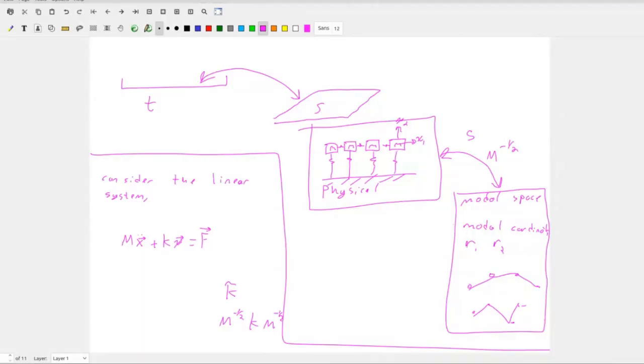And to do this, we're going to go down into our modal space, get a solution, and bring it back. And in the modal space, we can truncate modes that we're not interested in. Because if you go to a testing laboratory and you want to get a time series response to measure fatigue life on the wing of an airplane, how do you do that? You can do that statistically, but that's no fun. No one trusts the statistics. That's why those people make a lot of money and give you huge uncertainty. So you want an actual displacement so you can measure fatigue and do your Paris law, things of that nature.